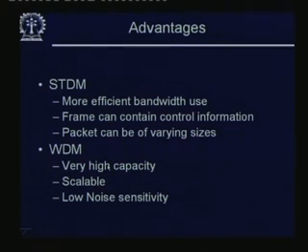WDM, we are writing it separately because although, as I said, it is some form of FDM, it works with very high capacity. It is scalable, and it has low noise sensitivity. That is another good thing about communication in the optical domain. If you are doing it in the electrical domain through a wire, and there is some kind of electrical noise somewhere, some motor has started, or, very bad, there is lightning somewhere nearby, a lot of noise will get into the electrical wire, whereas an optical fiber is not going to catch any of this noise. So, it is very immune to noise, which is very good, and it has very high capacity, and you can scale it to still higher capacity using DWDM and so on.